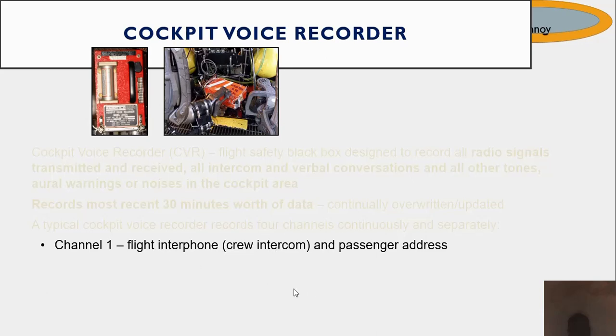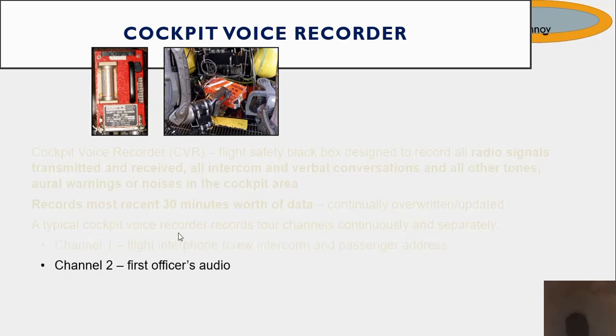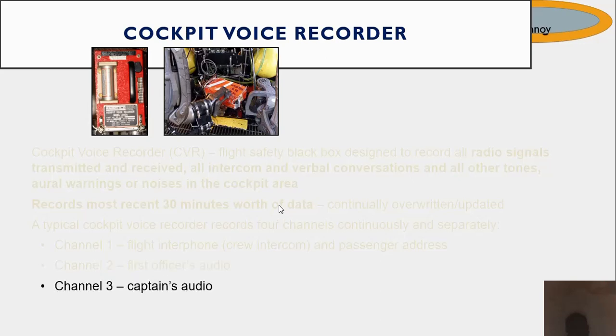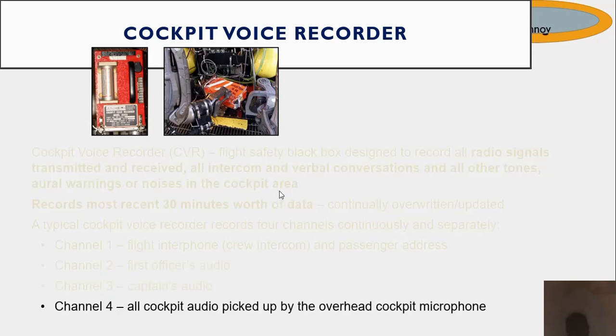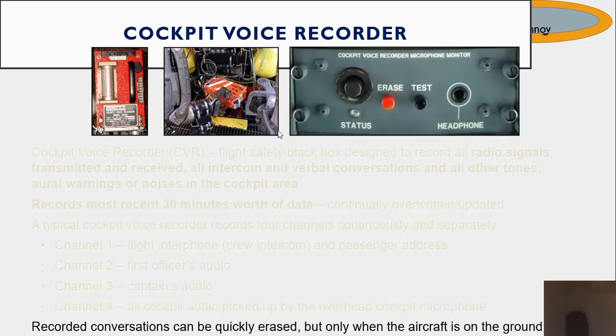We have channel 1, flight interphone, the crew intercom, and passenger address. Channel 2, the first officer's audio. Channel 3, the captain's audio. Channel 4, all cockpit audio picked up by the overhead cockpit microphone.